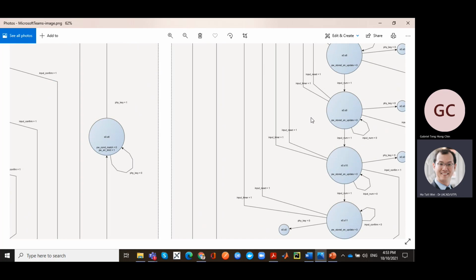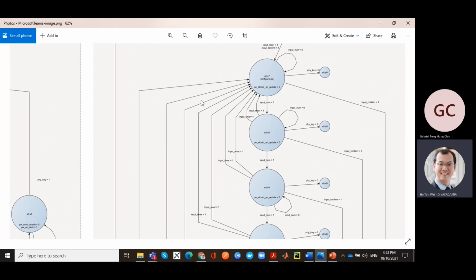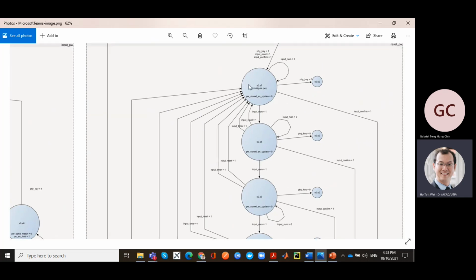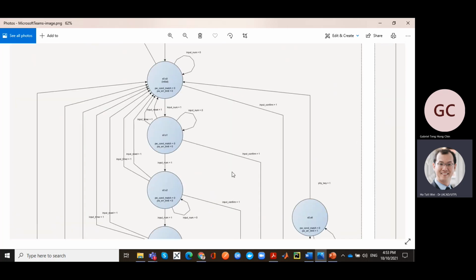So you basically will have 2 shift registers. One will receive the inputs and is clocked on input num. The second will be a shift register storing your password. So when you go into this branch, you're updating the second shift register. You go into this branch, you're updating the first shift register. You see where I'm going with that? Yep. That's one way to implement it.